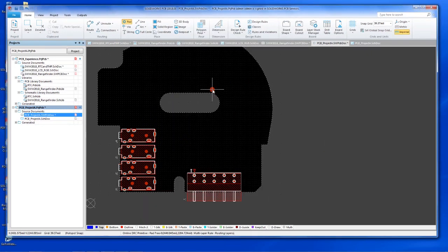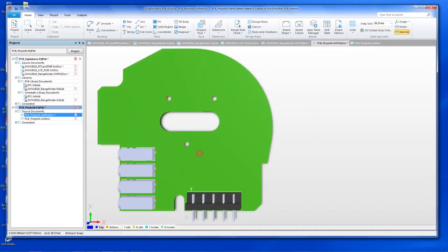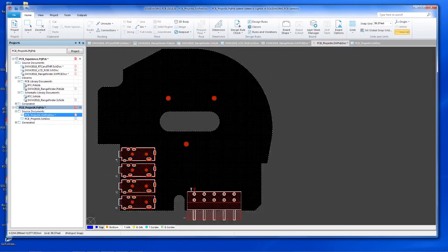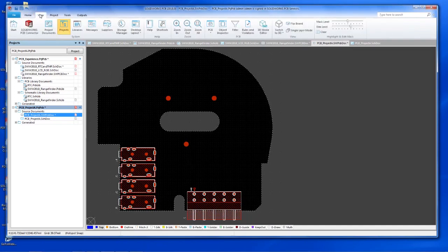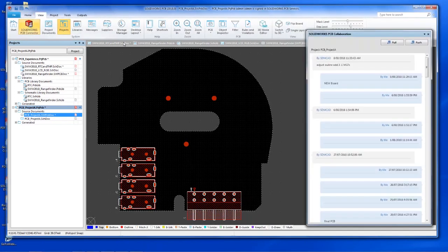Say OK. And we don't care where we put them in PCB. We didn't get any dimensions. We weren't instructed where to place them because we don't care. We'll let SolidWorks deal with that. Okay. So we added the parts, we added the holes, quick 3-dimensional view. That's kind of what our SolidWorks model is probably going to look like. So we can go now push this to SolidWorks.